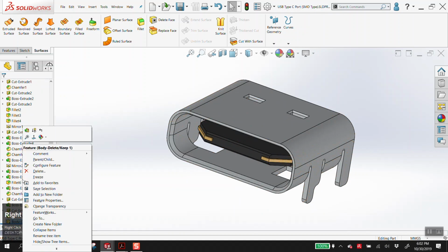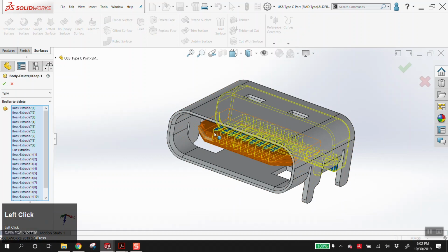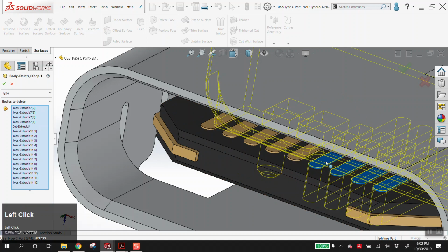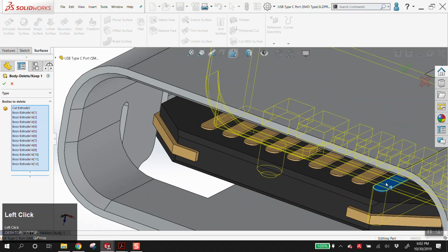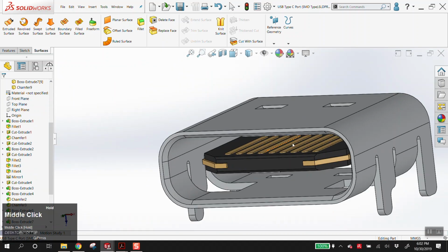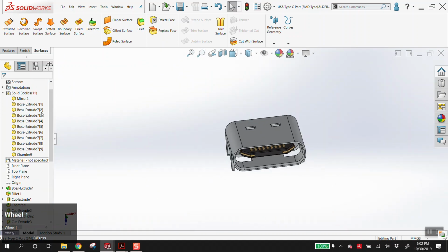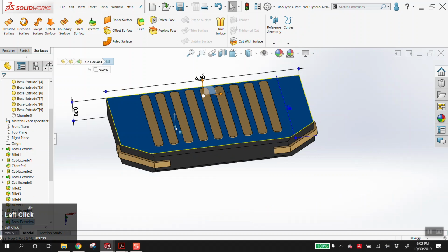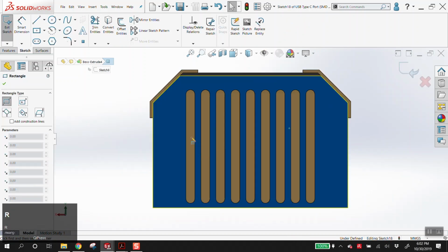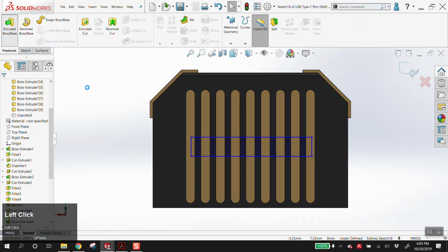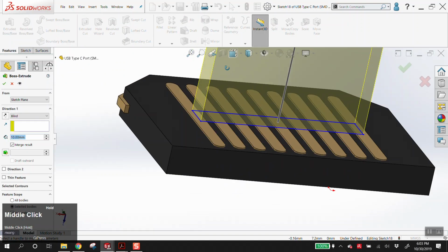If you want, unselect these ones because these are all visible. And to Max's point, you could extrude something so I can replicate. You don't need all the stuff in the back, honestly. So here we've simplified it, we cut it at least in half. But now we can simplify it further by creating a quick sketch on this face here, drawing a shape that combines all of these, and making an extrude. We don't want to see it though.